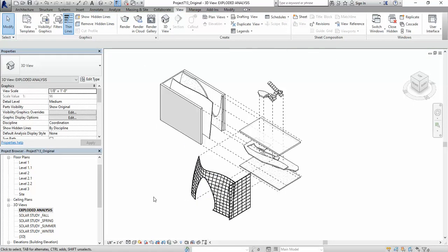so I could escape that, and I could export the view. Again, that's a very fast and even very generic understanding of how the explosion drawing could work. As I said before, you could categorize differently. You could say, you know what, I don't want all of the walls. I want first the exterior walls towards this direction, and then the interior walls towards the exact opposite direction. So you guys should feel free to select objects and displace them accordingly.